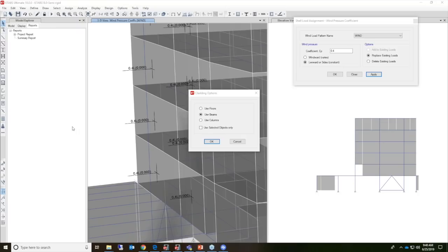Do we define one diaphragm to all levels, knowing that the slab thickness, hence the stiffness, will be different from one level to another? Yeah, you can assign the same diaphragm name to it. The program will actually have different diaphragms inside for calculation of the stiffnesses.